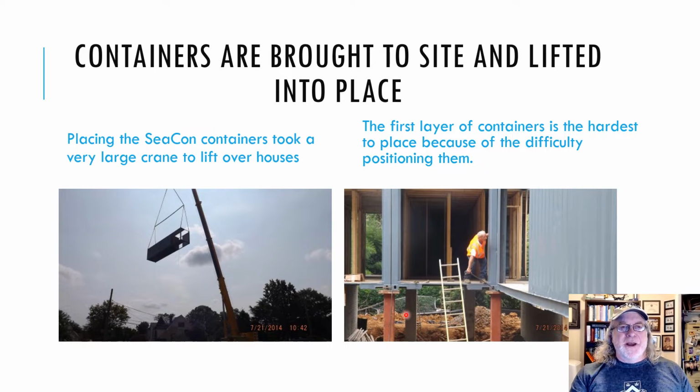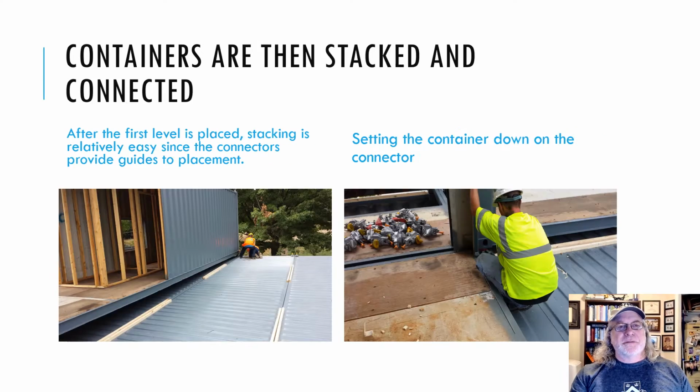And then positioning them in place in the first level is a pain. So the guy's prying here with a steel bar. That has to be done to get them in position. See how I've got these real thick plates that are oversized? Did that on purpose so you could slide these around a bit to get them in place so you wouldn't be threading a needle.